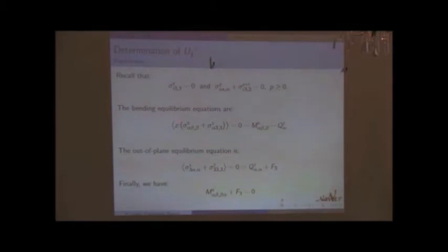And we do exactly the same trick we did yesterday for the equilibrium equation. Integrating the equilibrium equation at this order, you find that the shear force of order 1 is the divergence of the bending moment of order 0. And you find that the equilibrium for shear forces is the classical one, but it's for shear forces of order 1.